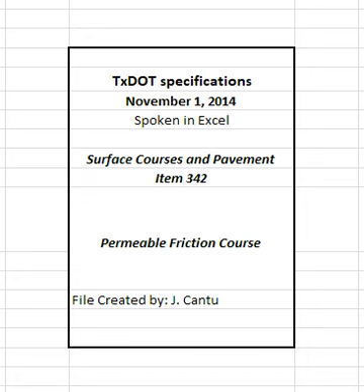Any stockpile that contains RAS will be considered a RAS stockpile and be limited to no more than 5% of the HMA mixture in accordance with Table 2. Certify compliance of the RAS with DMS-11000, Evaluating and Using Nonhazardous Recyclable Materials Guidelines. Treat RAS as an established nonhazardous recyclable material if it has not come into contact with any hazardous materials. Use RAS from shingle sources on the department's MPL.